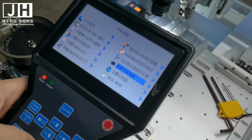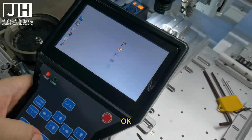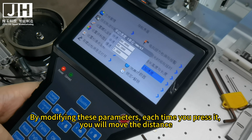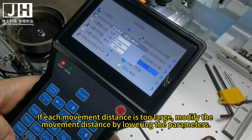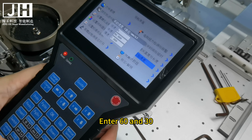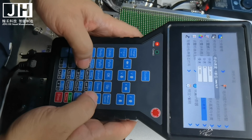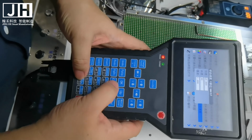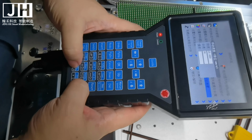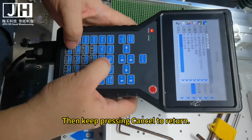OK. Select number key, manual speed. OK. By modifying these parameters, each time you press it, you will move that distance. If each movement distance is too large, modify the movement distance by lowering the parameters. Enter 60 and 30. Fast, medium, slow, 3 speeds to modify. OK. Then keep pressing cancel to return.